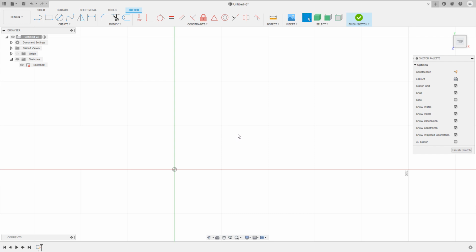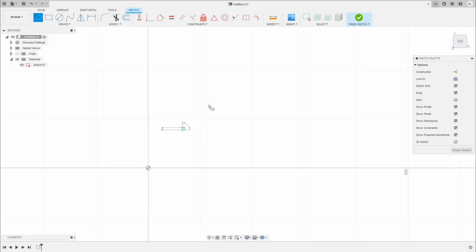When you press the shortcut key S, we get access to the sketch shortcuts window, and here the line tool is the first in the list. And it's also available when you right click somewhere on the canvas, go down to sketch and activate the line tool from here. And now I can continue to draw a few lines to the canvas,